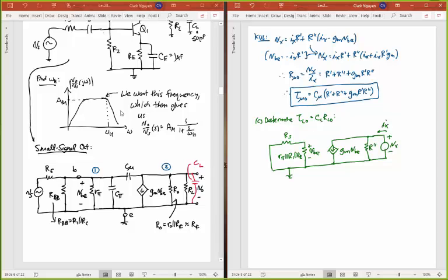And so if I look at this circuit, this whole thing on the left side, that's all grounded, right? So if that's all grounded, then that goes away, that goes away. And if this goes away, then I have no VBE, which means that goes away. And so in the end, the only resistance I see is just this R double prime. So I can just write right away that RLO is just equal to R double prime.